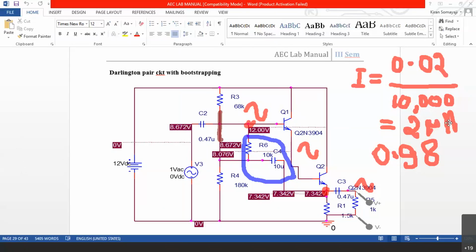Now, what is the conclusion here? Conclusion is there is a feedback of 2 microampere current in the AC domain. We are feeding AC signal, we are getting back the AC signal. Even though this looks like a positive feedback because the phase is the same, positive feedback is not going to increase the gain here, right? Amplifier gain is unity here. It will not become an oscillator now.